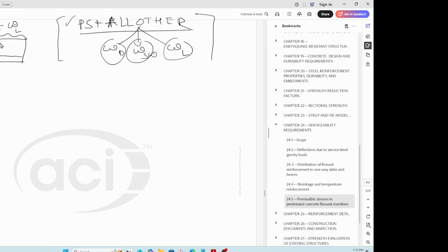So when that happens, again you can simplify it. There is a compressive stress in steel. Steel has already relaxed a little bit, so it has a final stress. Here is the neutral axis. You have your dead load moment acting like that.